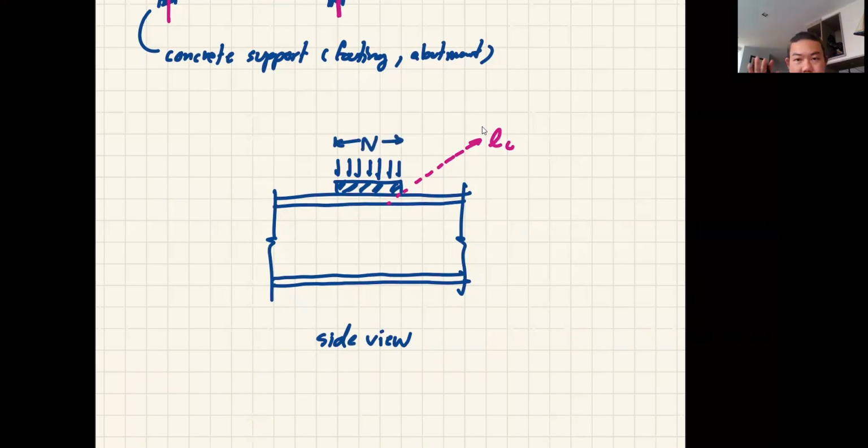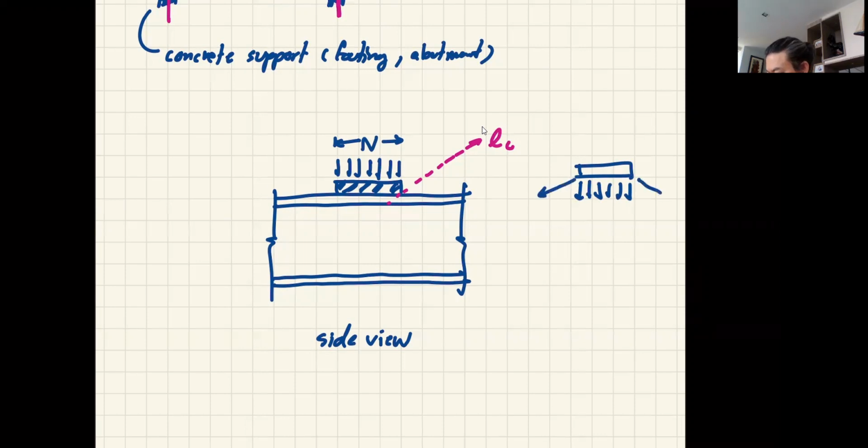But once you have the load acting on your structure, do you think the stress is going to go down directly? Say I have a plate like this, is the stress going to go down directly like that? It's like when you step on the ground, you think the stress from your foot will go directly like that? No, it isn't. It's going to be distributed out to the side like that.